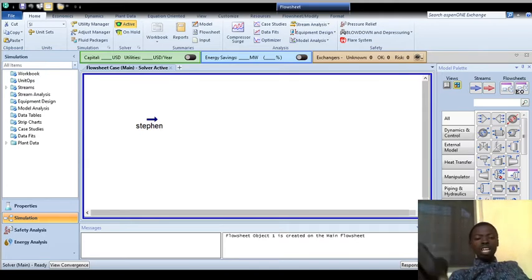The flow rate of the water is 100 kilogram per hour, and its outlet pressure from the pump is 84 bar. Using Peng-Robinson's equation of state as a fluid package, determine the outlet temperature of the water. If the outlet temperature of the water is 200 degrees C, what is the efficiency of the pump? How do we get that?